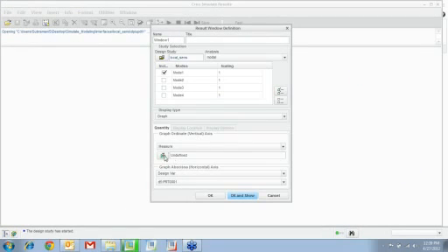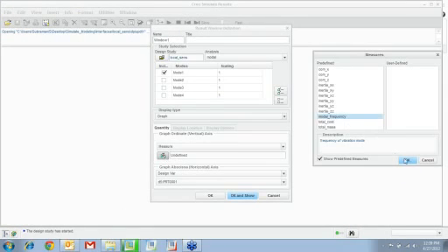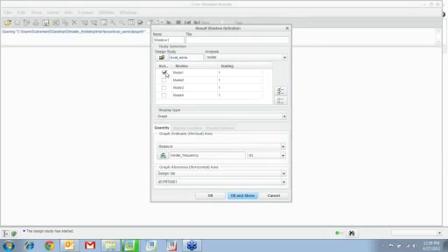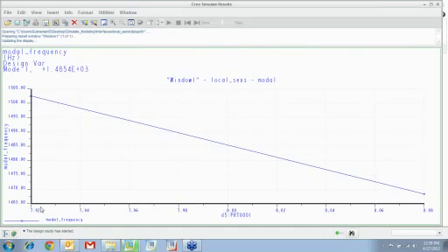So you can say, I want to plot the modal frequency, the first modal frequency, when I vary this design variable. You can see it runs it at 7.92, you can see that here, and 8.08, and you can see how it draws a graph. What it's trying to tell you is whether the modal frequency is going to increase or decrease as you increase the value from 7.92 to 8.